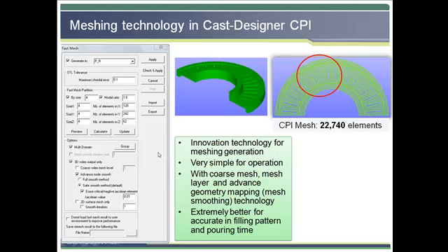We pay a little more attention to the meshing process, since it is always a critical issue and an argument between FEM technology and FDM or FVM technology. Cast-Designer is using FEM technology. It is more advanced compared with the traditional FDM or FVM method, because of the good geometry description, better formulation, fully coupled simulation, and flexible memory management. All of the above are very important for casting.